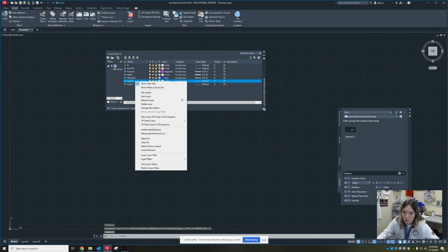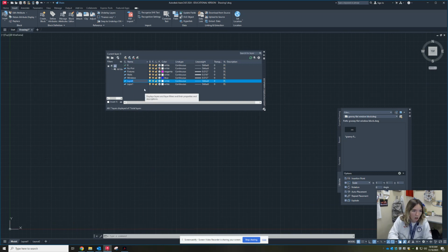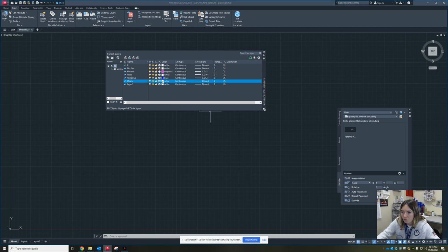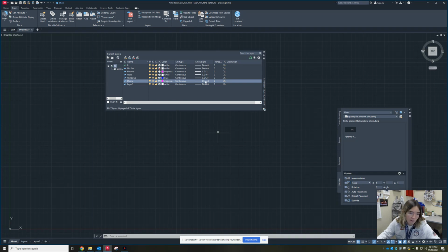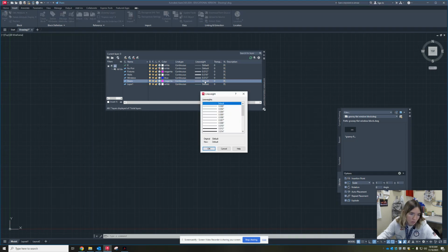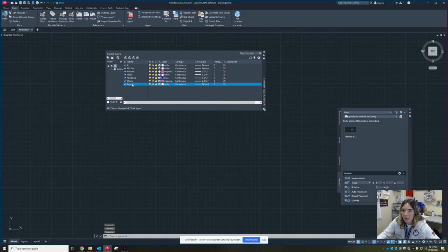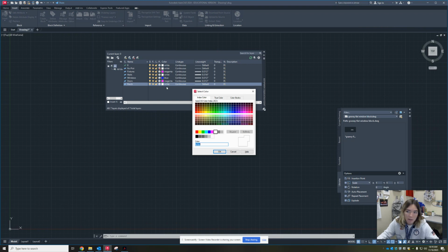And then the next one after windows, I'm going to rename a new one. Right click, rename. This one's going to be called doors. Doors is going to be magenta. Click OK. I'll change it from default for doors to 0.012 again. Click OK. And then the last thing we're going to put in here, layers wise, is porch. And I want the porch color to be magenta again.